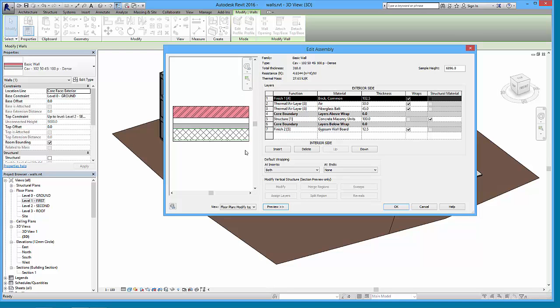And we'll see a little example later on how it's often perceived by people who use Revit that it doesn't matter if they drive through columns, even though that's not how they would be built. You would deal with that at a detail level. At 1 to 50 or 1 to 100 scale, it's more indicative of the positioning of these things and the relationship between sort of a wall and a column, for example.